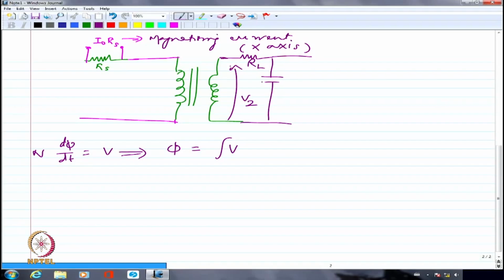So I am going to look at a resistance which is way too high as compared to the nominal or rated resistance that I may connect such that the rated current flows through the transformer. So RL is going to be much higher than the nominal rated resistance of the transformer. Not resistance of the winding of the transformer, I am talking about resistance which I will connect as the load resistance normally. So instead of 5.5 ohm, I may end up connecting 200-300 ohms.